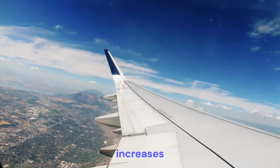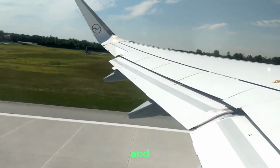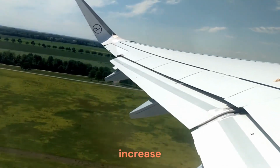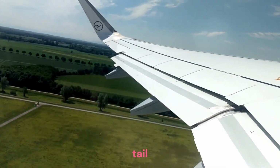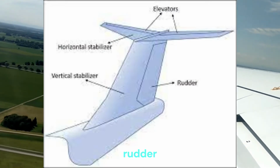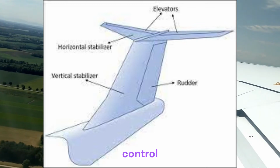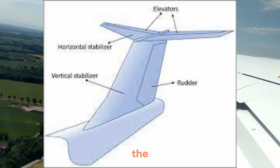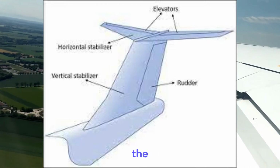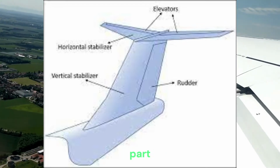If we activate the flaps and slats, it increases the downwash and increases the lift. The ailerons can move up and down, and for that reason, the lift force can decrease and increase respectively. At the tail of the airplane, you can see two attachments: the rudder and the elevators. By adjusting the elevators, you can control the vertical force on the tail. By adjusting the rudder, you can control the horizontal force.